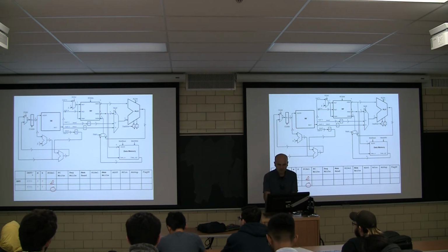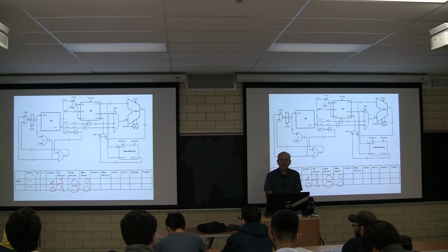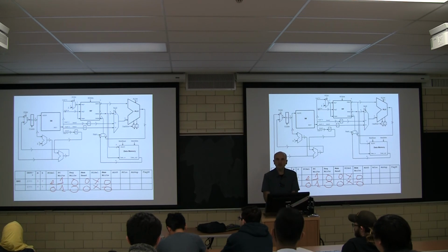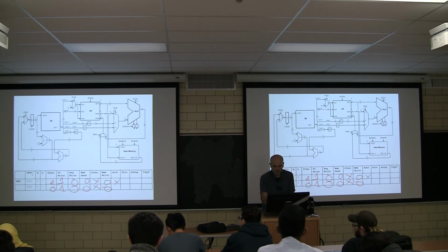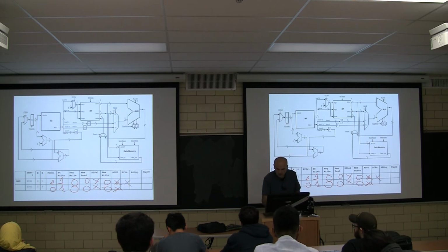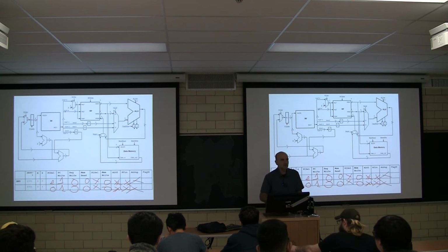Do we write to the PC? Of course we do. Do we write the register file? No. Do we read from memory? No. Do we care what the name of the register we're going to read from the register file is? No. Do we write to memory? Absolutely not. Do we care what the second operand of the ALU is? No. Do we care what the value is that we're going to send the register file to write? That's a statement a lawyer will make. We're not going to write anybody, so no. Do we care what operation the ALU will do? So 3 X's.